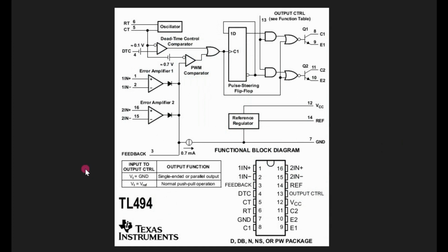I've gone back to the original diagram, and we have some features I want to talk about now. There are 46 active transistors and many diode connected junctions. We have a supply voltage that works up to 42 volts DC. There are 2 op-amp error amplifiers. There's a Brokaw band gap reference regulator.